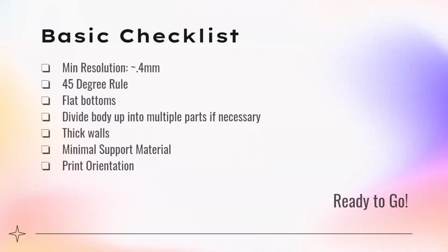So we have a basic checklist: minimum resolution, the 45-degree rule, flat bottom or slice the body in half, thick walls, minimal support material, and really consider your printing orientation.